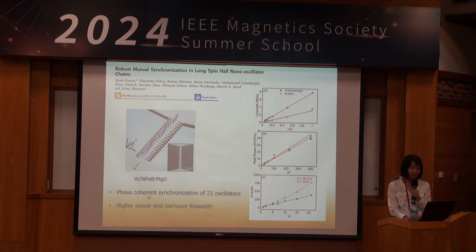They know these oscillators are coherently phase locked because the peak power grows linearly with n squared, n being the number of oscillators. So there's a coherent adding of the amplitude for the emission power. And as the power grows, there's also another benefit. This is the line width, plotted as 1/n. A larger number of oscillators is in this direction on the left. So the larger the number of oscillators you phase lock, the narrower the line width you get. This is desirable for a lot of applications.